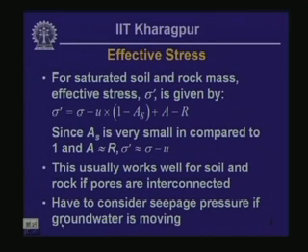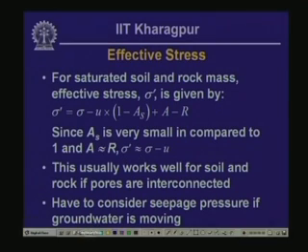What we could write is sigma prime is equal to sigma minus U, or the effective stress is equal to the total stress minus the pore water pressure.